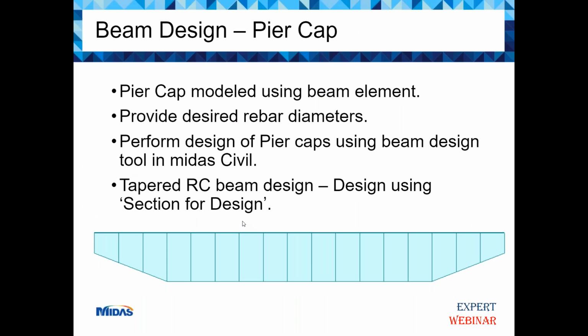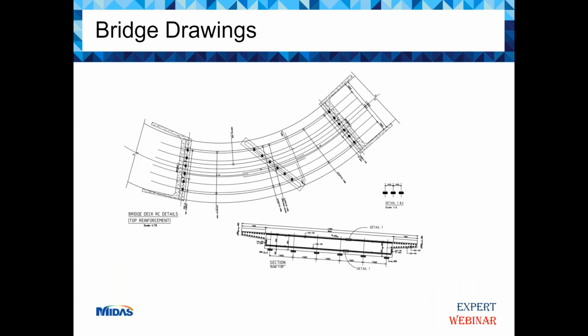These are some of the drawings that we got, or we drew. We used bundled bars. If you've seen in the design, we realized that using just a single bar would not work. Otherwise, the stresses were very, very high, especially in the area that is spanning 21 meters. So we had to opt for using bundled bars and increasing the strength of the concrete.